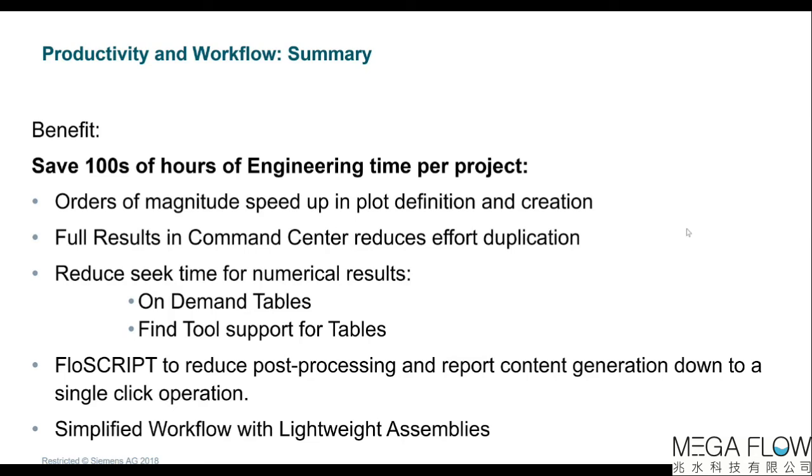You can expect to have reduced seek time for numerical results, and that comes in two formats. So first would be the on-demand tables, so the point-and-click approach to getting the numbers that you need, and also that fine tool support for tables. The last demo that we saw was that flow script functionality to reduce post-processing and report content generation time down to a fraction of the time it used to take in previous versions of Flotherm.